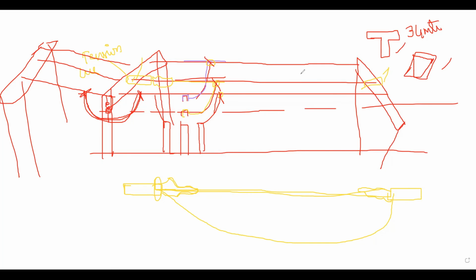Suppose I am having a conductor. This is the conductor which is traveling on the top, which is ACSR moose. I am having a conductor on the bottom, which is here. The equipment is there, lightning arrestor. The conductor I am taking, this one is ACSR Panther. So I have to choose a T connector, which is forming a T shape.